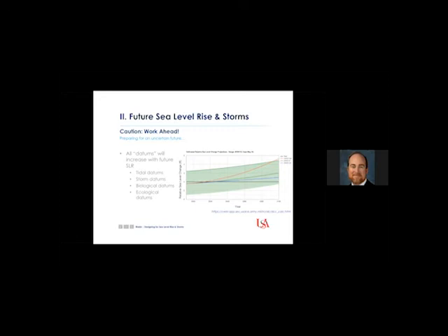Now, also related to future sea level rise, as mean sea level increases, all of your datums will also increase along with it. So your tidal datums, mean low water to mean high water, are going to shift along with that change in mean sea level. All of your storm datums. So everything that we use right now in the context of design related to still water elevations, whether it's flood-based design or ecosystem-based design, those storm datums are also going to change with future sea level rise, and sometimes in a nonlinear fashion.